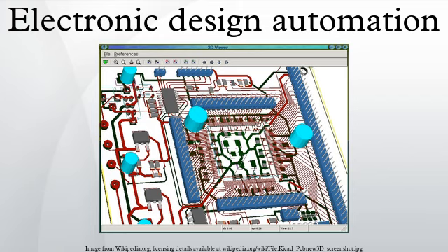Automatic test pattern generation, ATPG, generates pattern data to systematically exercise as many logic gates, and other components, as possible. Built-in self-test, or BIST, installs self-contained test controllers to automatically test a logic structure in the design.